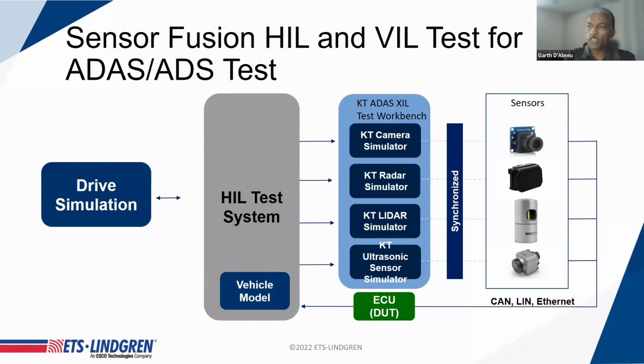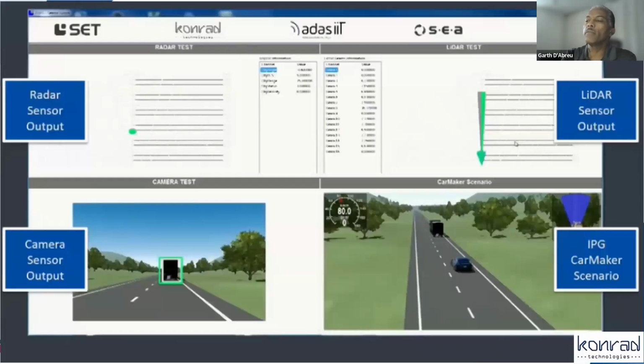Manufacturers have obviously progressed in the use of the sensors that are used for very many of these ADAS features. And whereas before a lot of the adaptive cruise control and emergency braking was related to the use of radar, most of them now use fused sensor systems where it relies on inputs from video cameras, either mono or binocular cameras, in addition to one or more radar sensors.